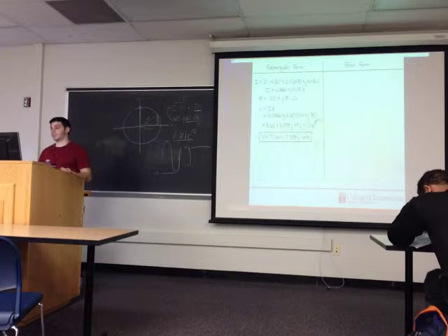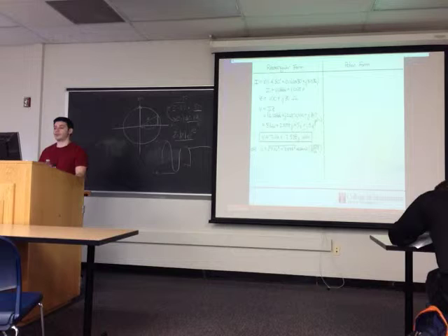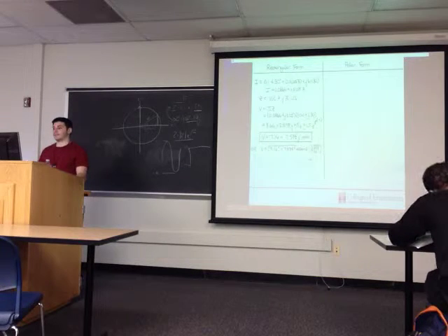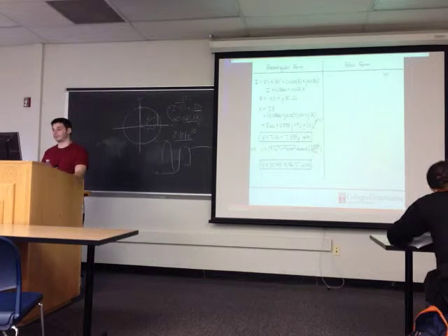And this is rectangular form. If we wanted to represent it in polar form, we would find the magnitude and the phase using the square root of each value squared and the arctangent of our imaginary component over our real component. So that would be the result for rectangular form and polar form.